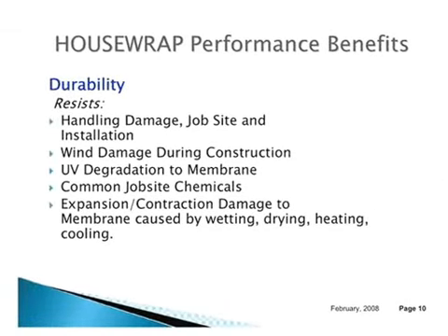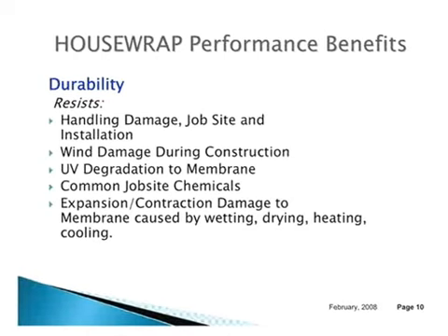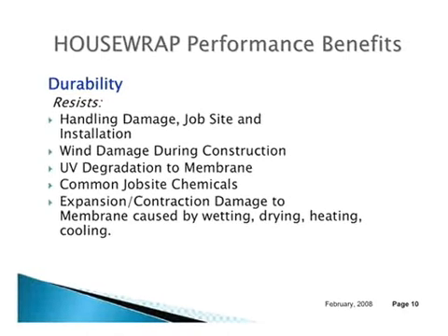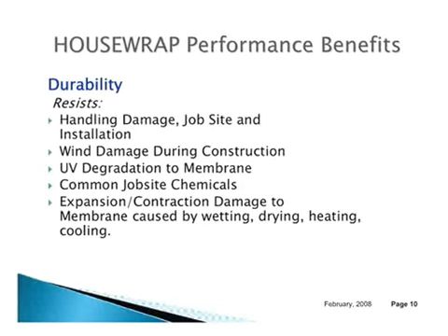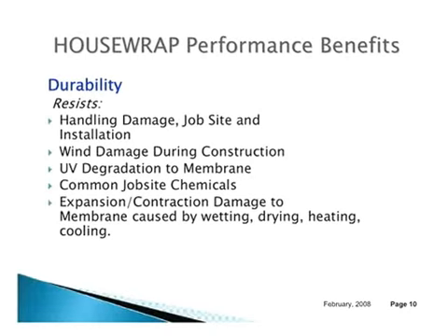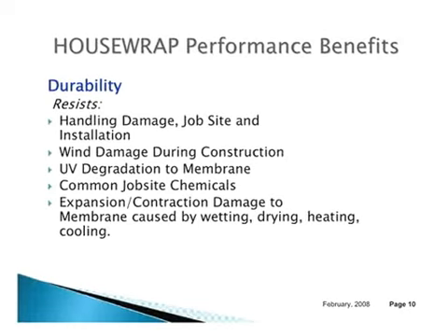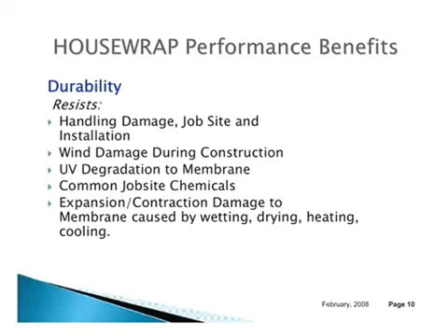Durability is an important characteristic of Housewrap because the way it's made, it will resist handling damage, whether this be on the job site or during installation. The Housewrap material is going to be subject to the weather conditions on the construction site until it's covered up with the cladding system. So having a stronger membrane, you'll have less damage due to wind.